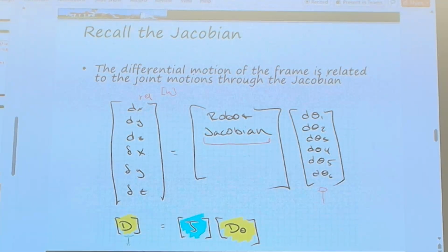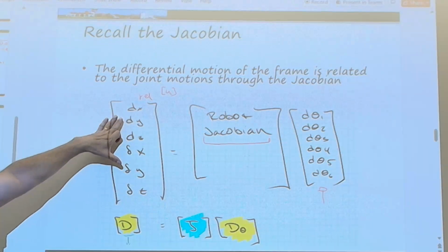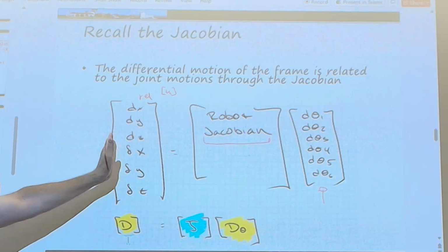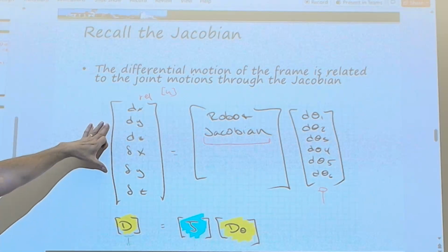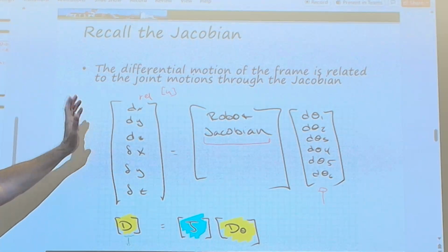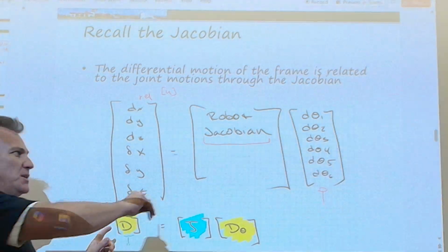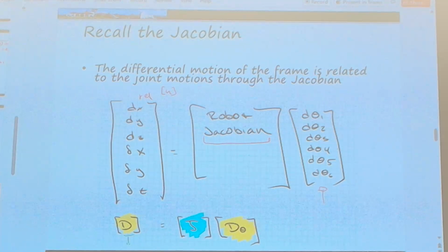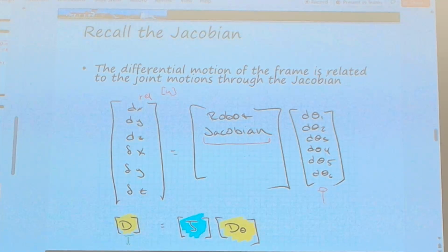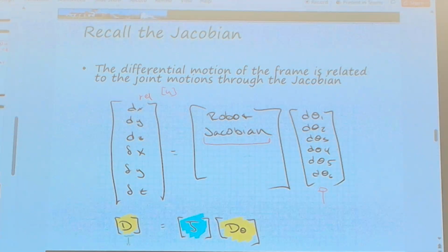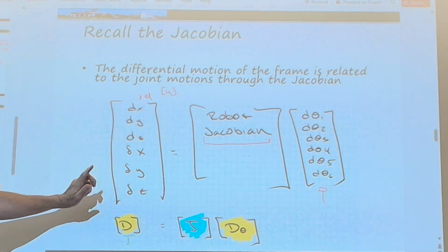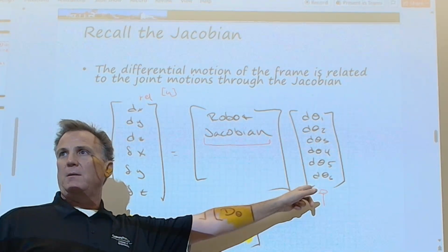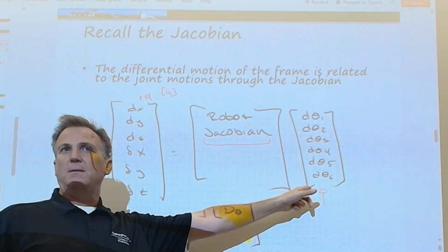No, not quite. Mathematically speaking, because I don't have a 1-to-1 relationship through this Jacobian, because I've had these little changes over here, there's no guarantee that that's going to be where I want it to be when I integrate this over time to position. So that means I can still do a position, but the position is driven by these theta velocities, not so much the thetas. So we can still do a PID position or a position controller, but we're driven from the error from these positions, not this space, even though this is what we command. Does that make sense? Now does it make sense?